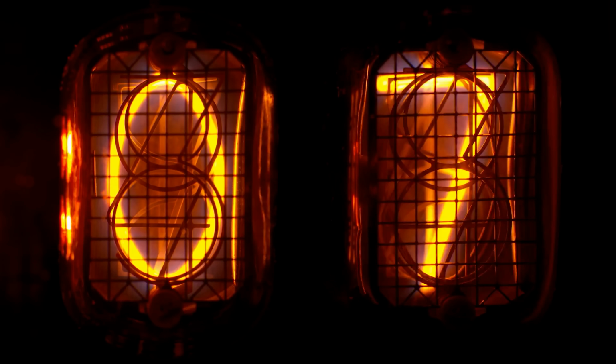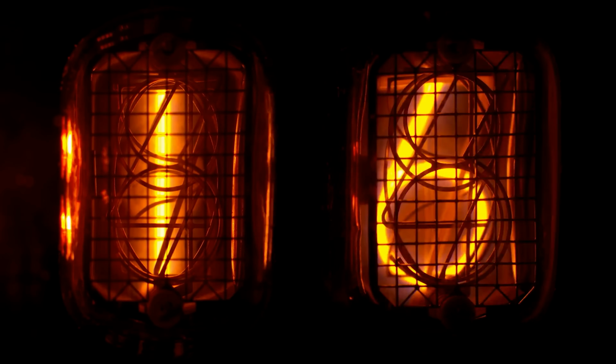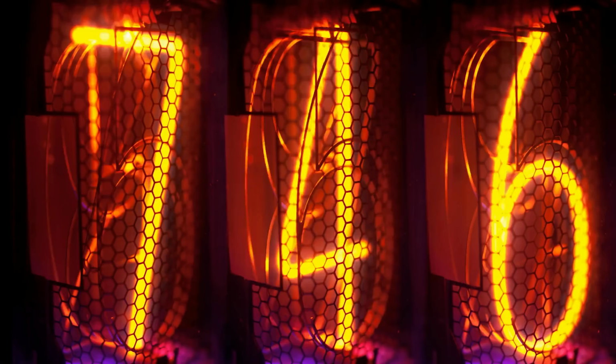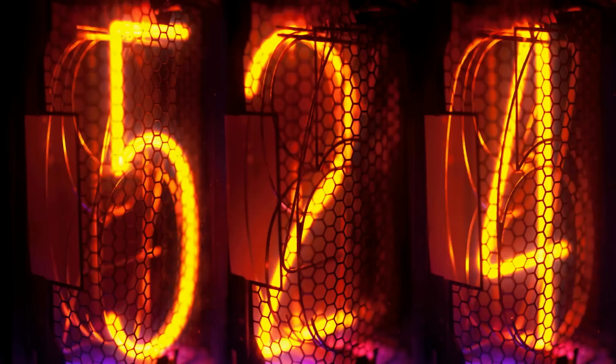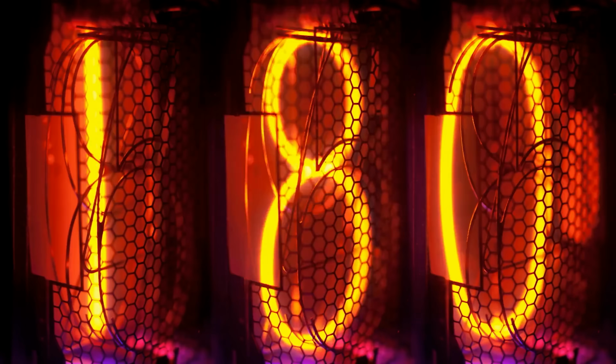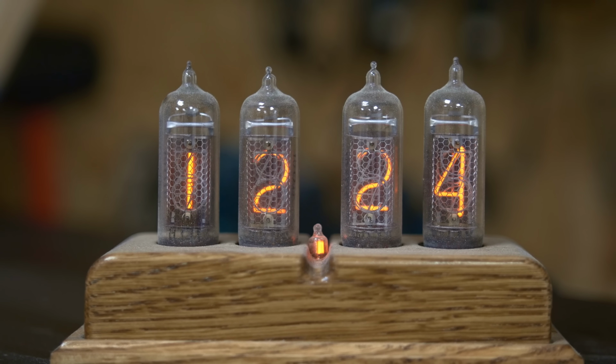Over the years, equipment manufacturers tried all sorts of ideas. One of the most famous is the Nixie tube. These neon-filled tubes produced a glow discharge around wire cathodes formed in the shape of numerals, resulting in beautifully legible displays which were readable in many conditions. But they had a rather huge caveat. They required high-voltage DC to produce that discharge. As in, around 180 volts. That meant that while the tubes were simple, the circuitry required to drive them was complex, not to mention dangerous.